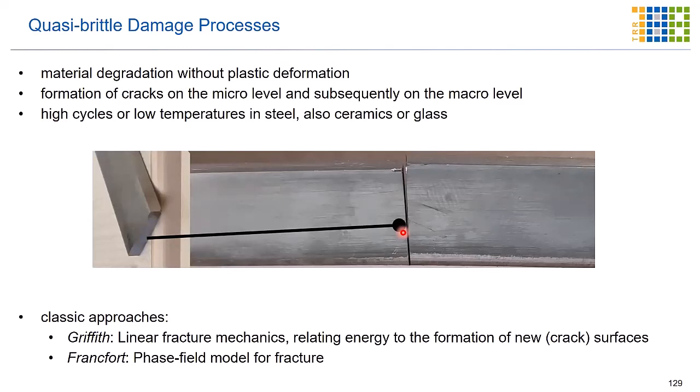Classical approaches we find here is, again, Griffith, that relates this damage type to the energy of the formation of new crack surfaces. And for the numerical implementation, we have an important contribution, for instance, in the form of phase field models for fracture.